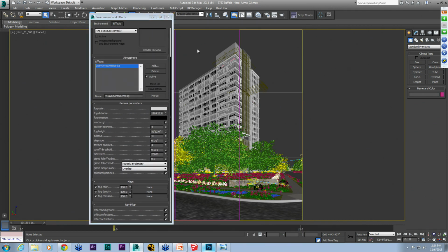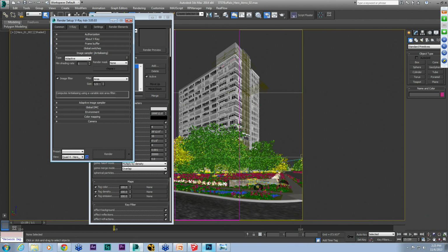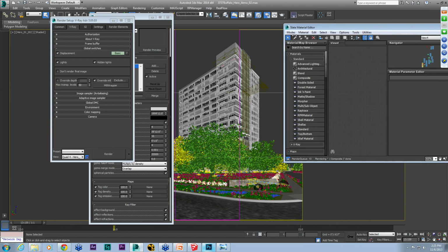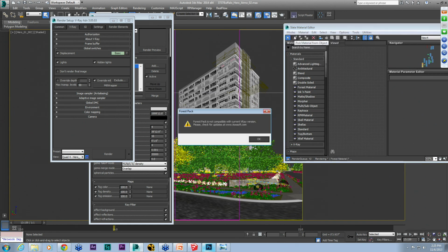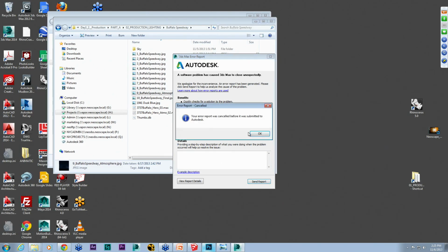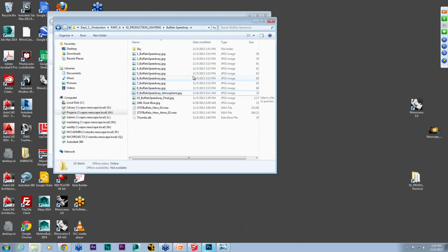Let's see what material I used. Whoa. Okay, so I used a material wrapper here. Don't crash me. Every time. All right, I used a material wrapper though, and it's basically the same thing as setting things as a matte object through the V-Ray properties, where you right-click it and tell it not to affect the alpha. But you can just do that globally with the material wrapper.